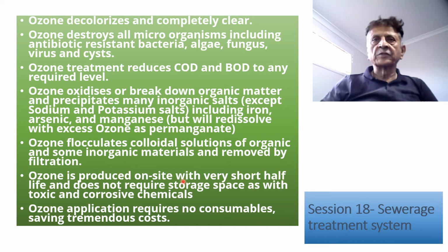Ozone is produced on site. It has a very short half-life, and therefore it cannot be stored, and so does not require any storage space or toxic and corrosive chemicals. And ozone application requires no consumables. You can save a tremendous amount of cost. So this is just a summary of the treatment.